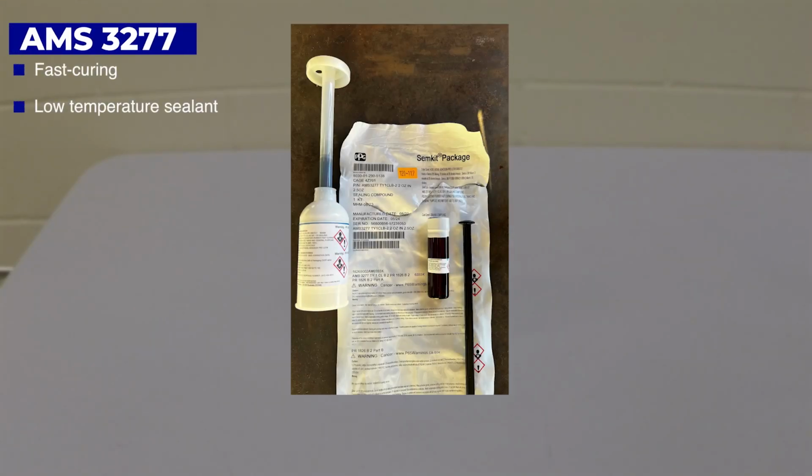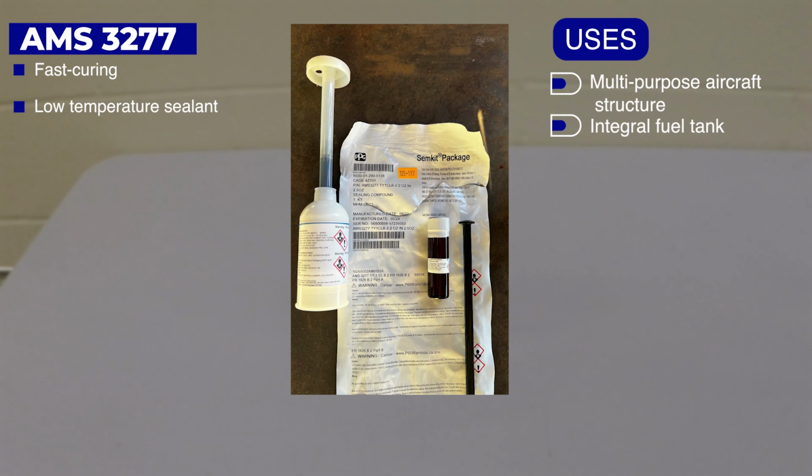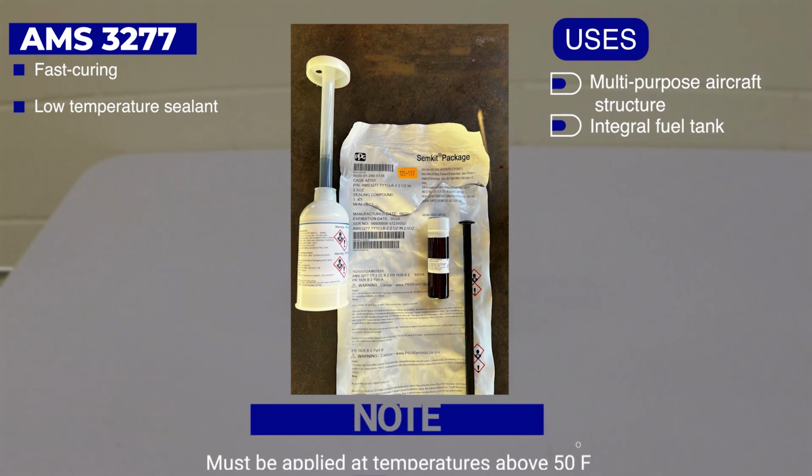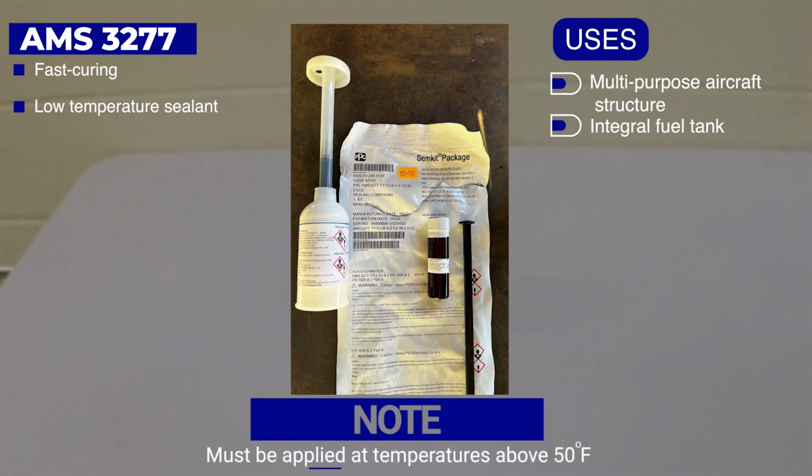AMS-3277 is a fast-curing sealant used for integral fuel tanks and general purpose up to 360 degrees Fahrenheit. It is a multi-purpose aircraft structure and integral fuel tank sealant with rapid ambient and low temperature curing capability. Type 1 must be used with the supplied adhesion promoter. It is not recommended for use with plastics. This sealant must be applied at temperatures above 50 degrees Fahrenheit. It can cure at temperatures as low as 20 degrees Fahrenheit. No corrosion inhibitors.